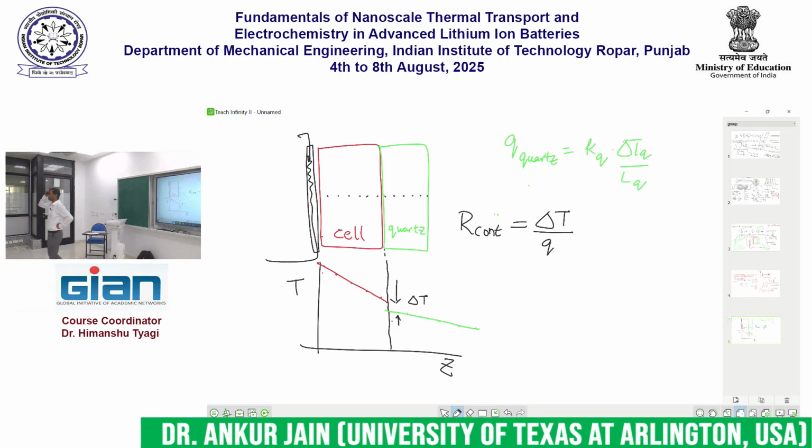Yes? We are making a perfect contact, and how will we place our thermocouple at the interface of each material? That's a good point. We are not placing thermocouples at the exact interface between the two materials. We are trying to get pretty darn close, right? But at the end of the day, we are going to extrapolate this curve and meet the two curves at the intersection.